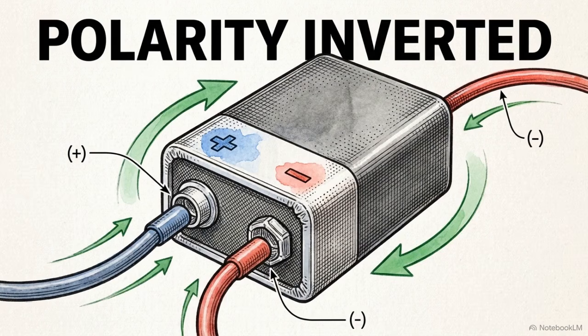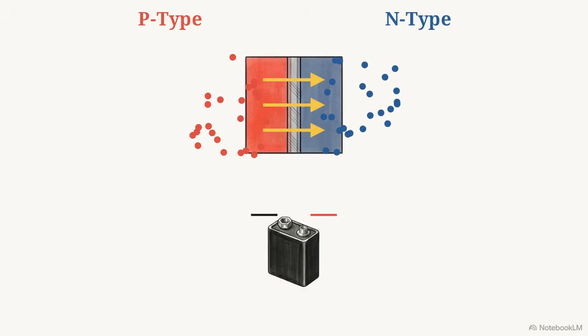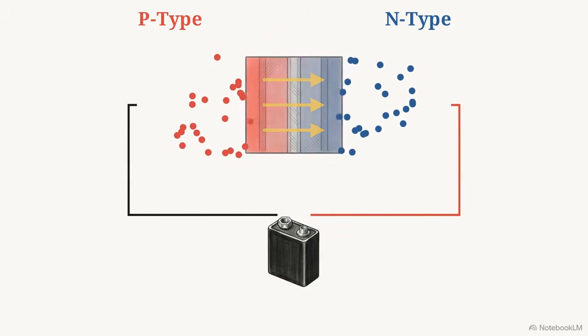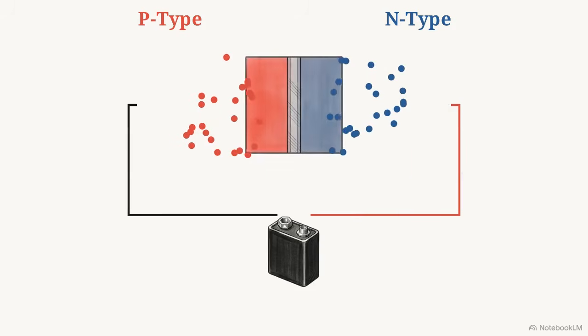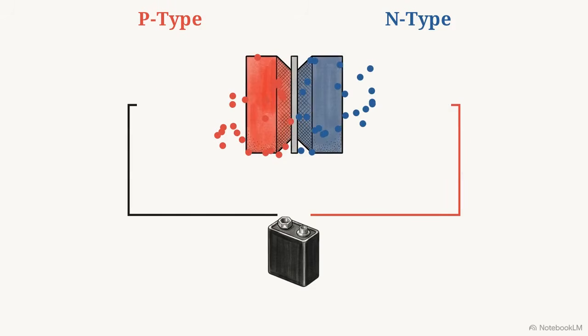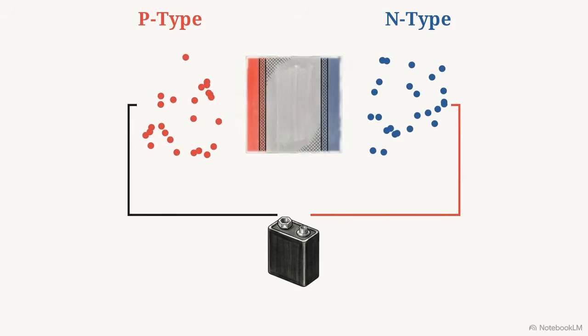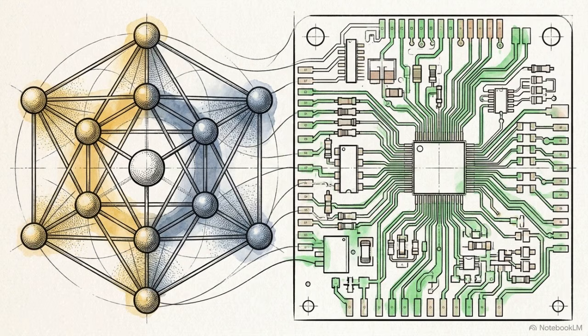Reverse bias occurs when we flip those battery connections. Reversing the polarity violently pulls the charge carriers away from the center junction. The depletion region tears vastly wider. The main current drops to zero. A microscopic leakage current persists, but this is only due to ambient thermal energy generating rogue carriers. The diode's ability to act as a switch is governed entirely by whether external voltage shrinks or stretches this atomic dead zone. These microscopic atomic movements map directly onto a macroscopic engineering tool.